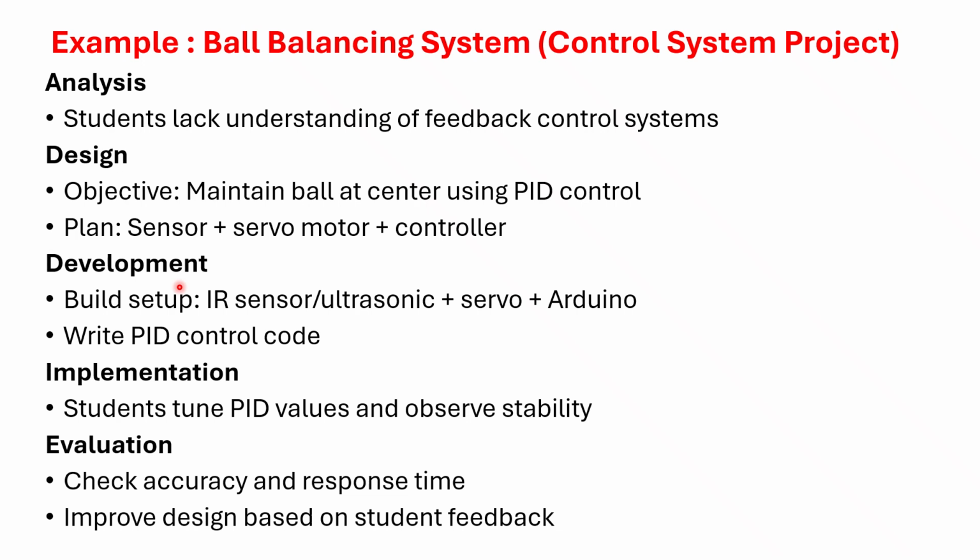The next phase is the development phase. In the development phase, the students have to build up the setup. As I already mentioned, generally the ultrasonic sensor is used, and we can also use an IR sensor for sensing the ball position. Based on this, the servo motor is actuated and the controller will adjust the ball at the center position. So for this we need a PID controller code. So write the PID control code, and during the implementation phase the students should tune the PID values and observe the